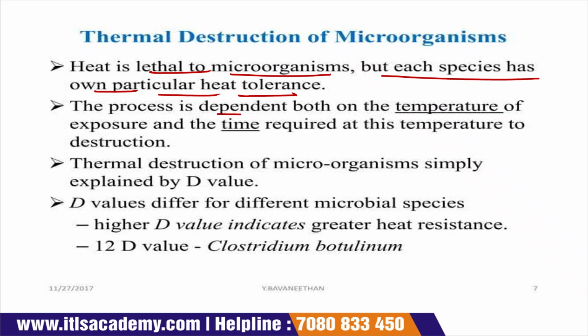The process depends on both the temperature of exposure and the time of exposure. When we apply heat to the food product, the destruction of microorganisms depends on two things: the temperature exposure and the time required, so that the temperature can penetrate inside the microorganism and destroy it.